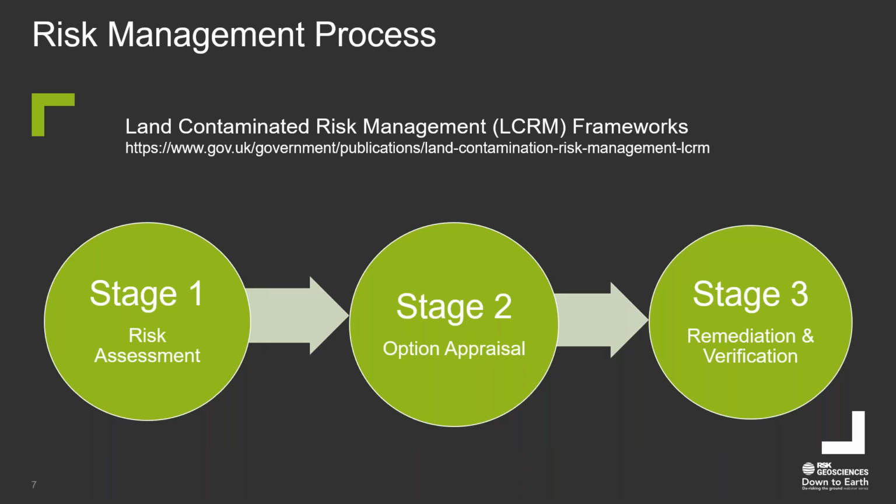There we will screen the feasible remediation options and do a detailed evaluation to select remediation options for our sites. And then in stage three, we develop the remediation strategy, and then do the remediation, and finally we verify the site to confirm that the remediation objectives have been achieved. So very briefly, this is the risk management process, and you may have to follow it from the beginning to the end if you are going to remediate the groundwater beneath the site. In general, this is the approach.